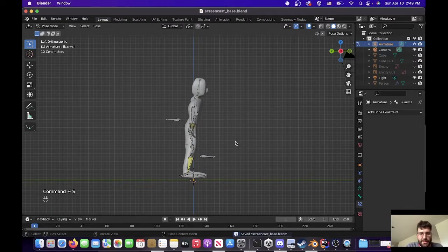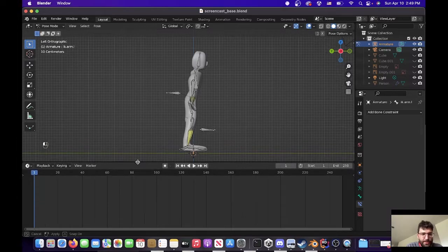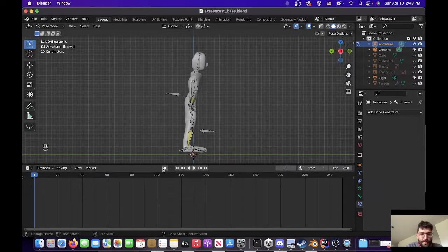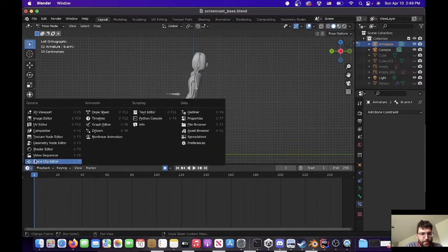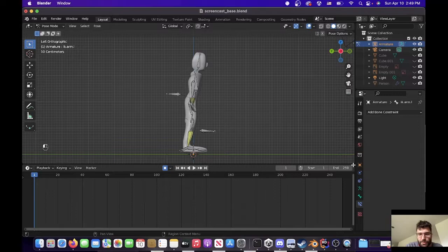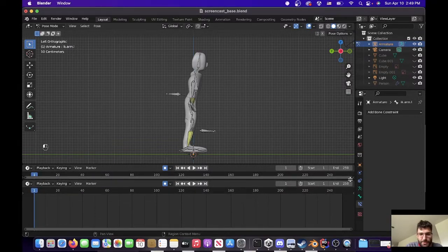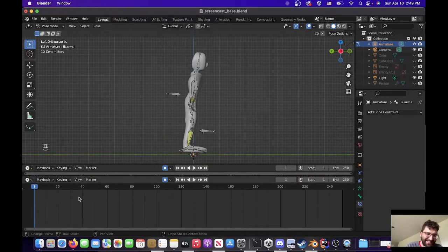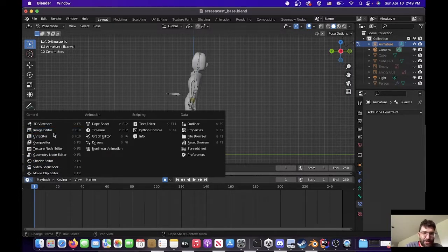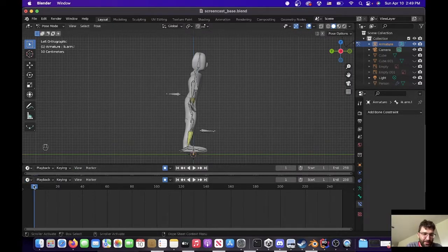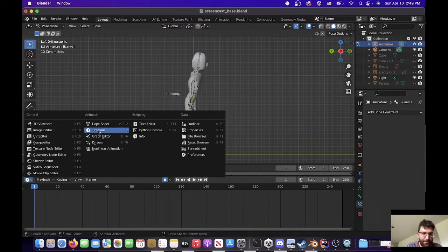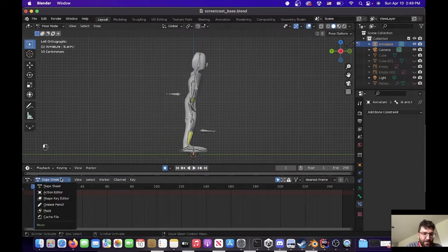So now we're gonna get into something called actions, which is, guess what? There's even more to Blender. This button right here records keyframes. Keyframes are like, you know, the extremes of poses and things like that. But I need to make a new window. Don't ask how I'm doing this. It's very confusing. If you drag down to the top corner, you can duplicate windows, and that's valuable. Go to Dope Sheet, and then from Dope Sheet, go to Action Editor.